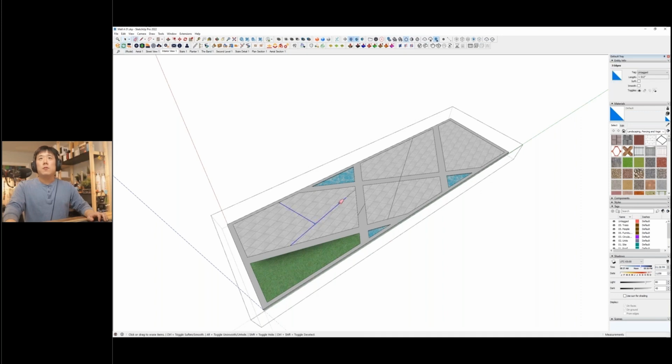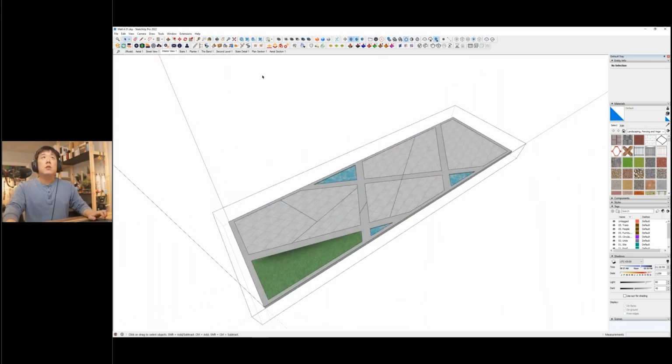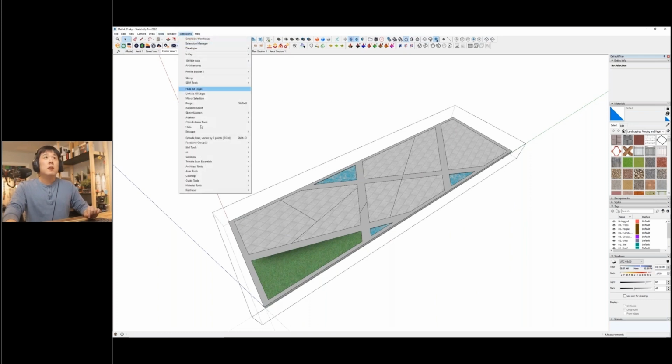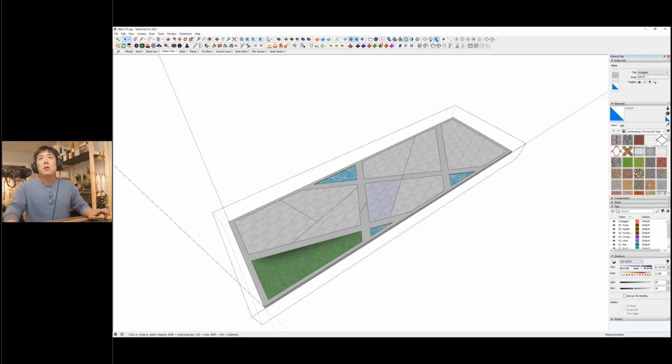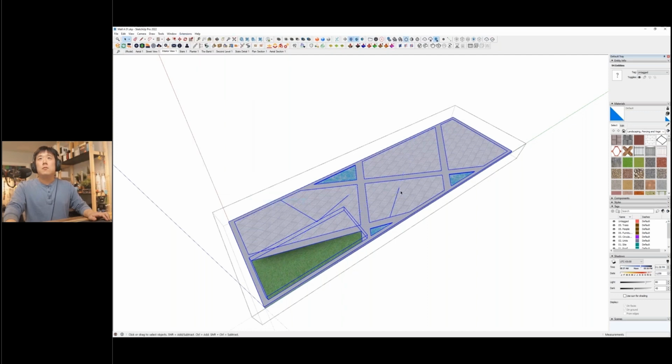I can go through with the eraser tool to go over them and clean them up. But if you have hundreds or a lot more of these, then they are difficult to go through. So a couple of extensions that you can use: one is from TomTom, and if you go to the extensions, once you install Cleanup, you'll have an option, Merge Faces. You can select all of the ones that you want to merge faces with, and then hit this, where I have a shortcut of Shift W on my keyboard.